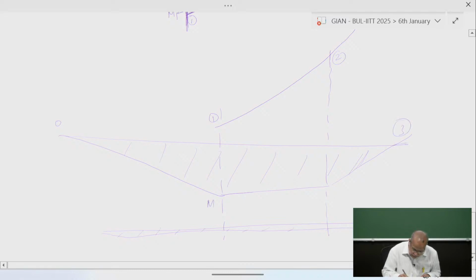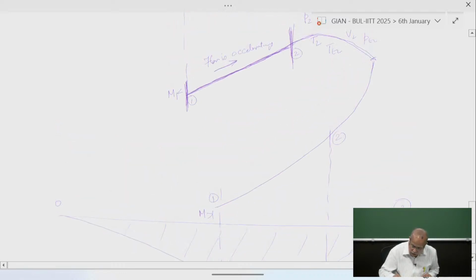So here M is greater than 1. The lower branch of the Rayleigh line is supersonic. The addition of heat will cause the supersonic flow to decelerate. Eventually in the theory it will reach M equal to 1, which is the critical condition. That is the theory.